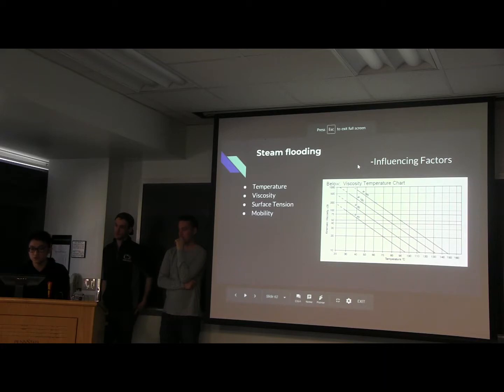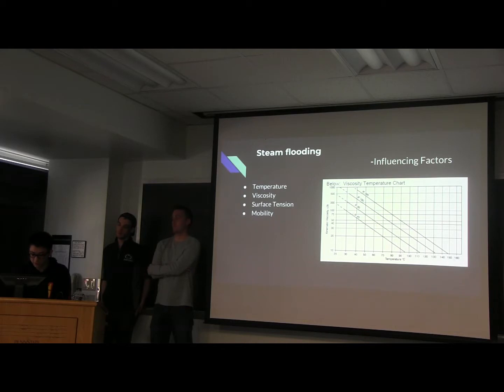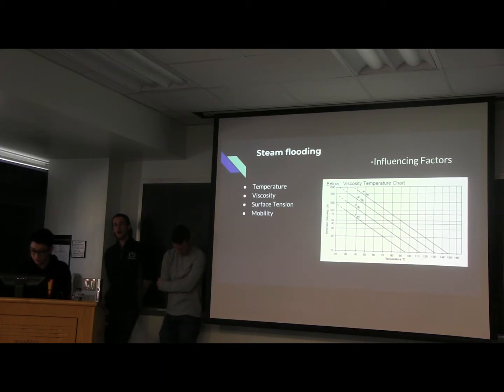And for the influence factors, the injection of the steam heats the crude oil in the formation, thus lowering its viscosity and vaporizing some of the oil to increase its mobility. The decreased viscosity helps reduce the surface tension, increase the permeability of oil, and improve the reservoir seepage conditions. Oil vaporization allows oil to flow more freely through the reservoir and to form a better oil bank once it has contact.